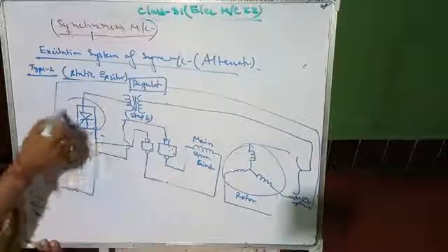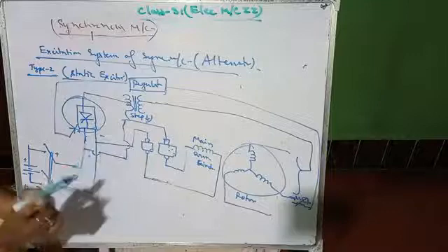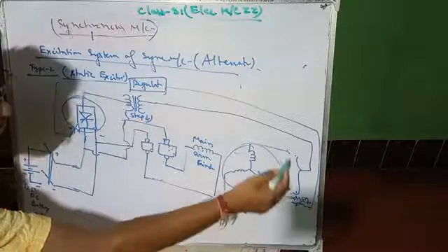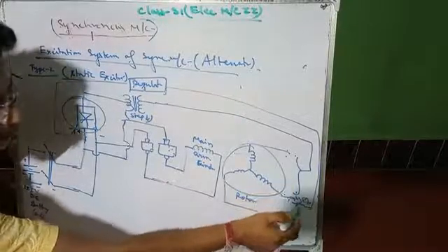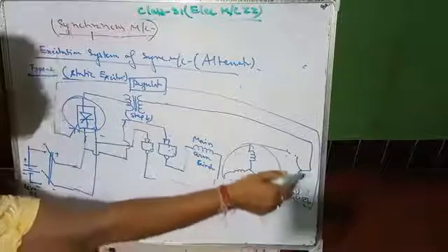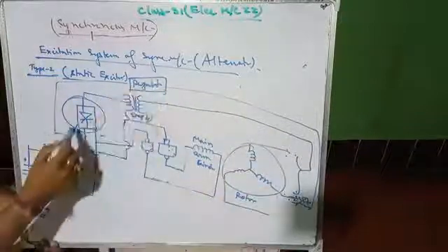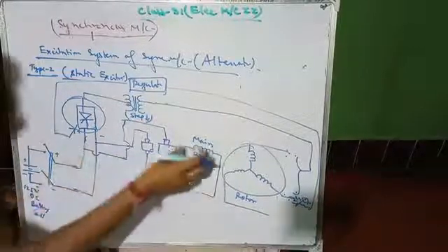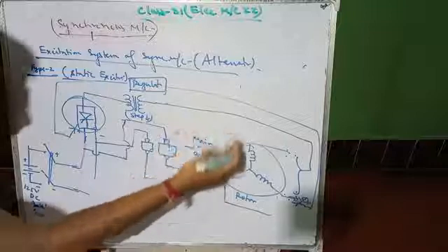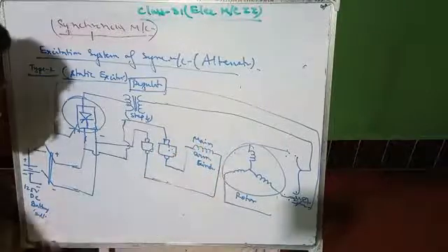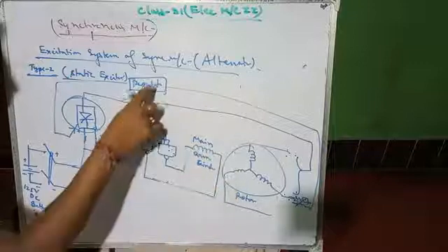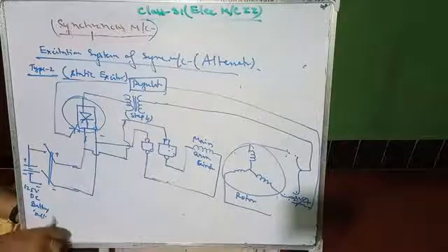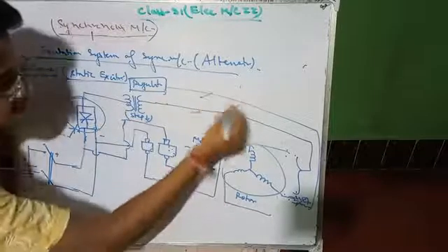So this thyristor will be controlled by controlling two operations. The voltage reading from the rotor part, that is the field part of the alternator, and the current flowing through this output will be regulated by a regulator, and it will be triggered by this concept. Simultaneously the main armature field will generate a flux to rotate the rotor part. As the rotor is rotating, this regulator and step-down transformer are actuating, so the thyristor will be triggered when it is required. So this is the feedback control path.